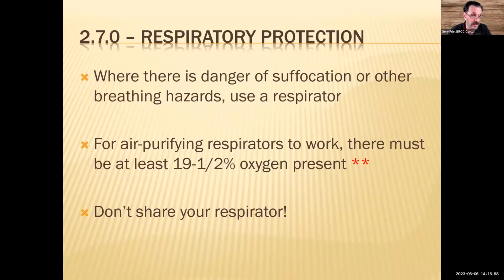So if you don't have at least 19.5% oxygen present in the air, and you have to test for it to know that, then you shouldn't be using an air purifying respirator. You need to use a supplied air respirator of some sort. And these things shouldn't be shared, of course, because you'll spread germs and such.